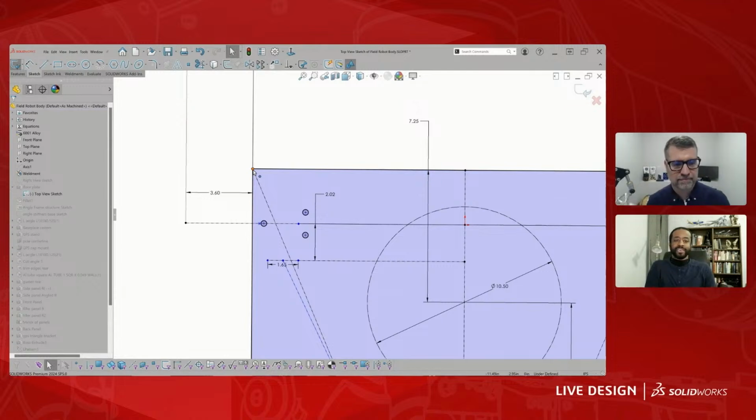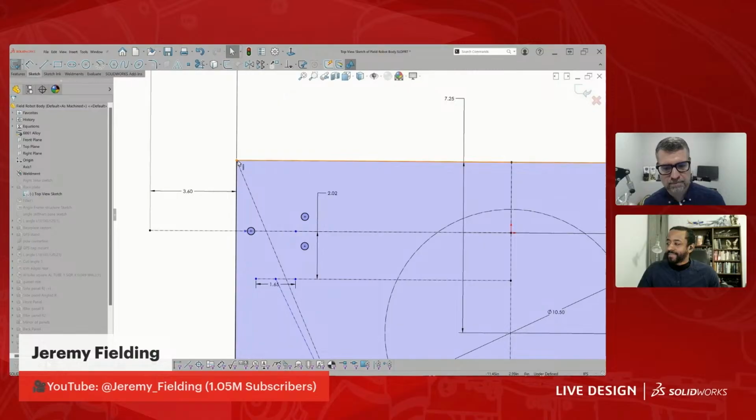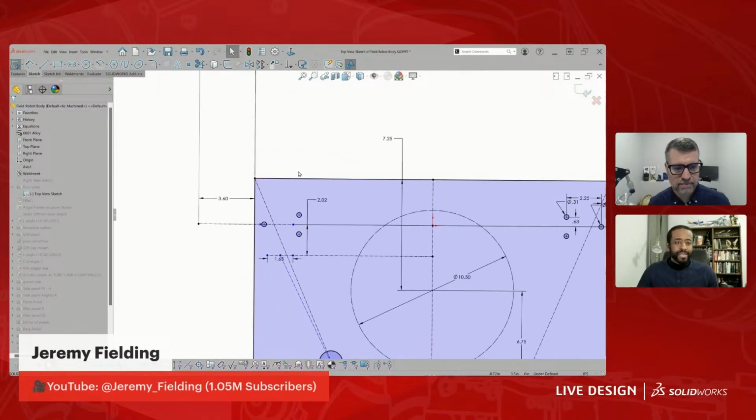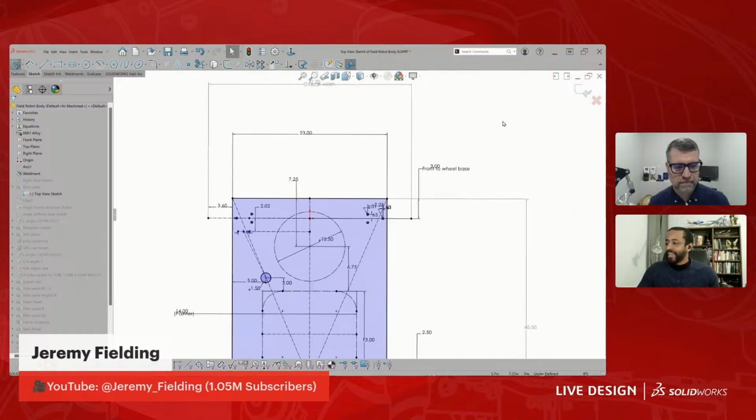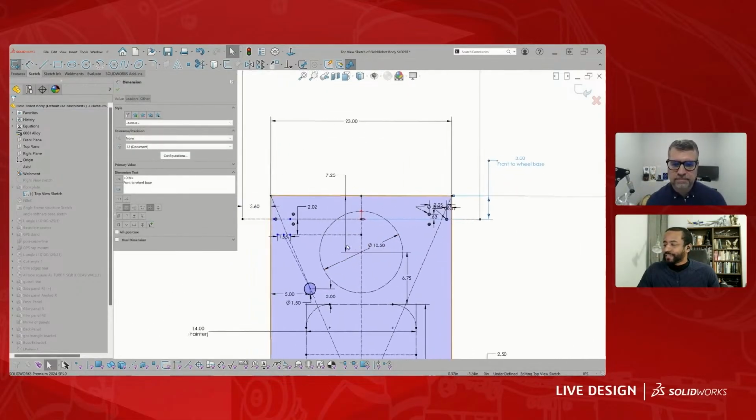It's much more detailed and you can watch it over and over. But if I base that boss extrude from this point, it won't just vanish. It won't ever lose its foundation. It'll stay in place until I'm ready for it to leave. And you can also add names like overall width, to define what these sketches are for.